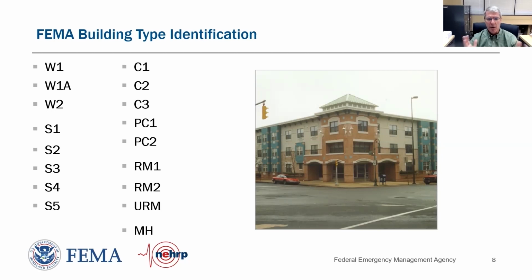Anything else? How about overall materials in terms of, can we eliminate anything there? Is it wood, steel, concrete, or masonry? Any of those materials we can, you know, systematically take out right away. Well, I think wood buildings can go up to 3 stories, but I'm thinking it might not be a wood building. I would think it could be concrete. It could possibly be steel, although I'm not sure that that's very likely. And I don't think that it's reinforced masonry with all those bump outs. That seems like that would be difficult construction.